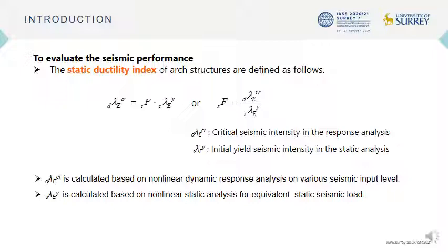Here, dλE critical is a critical seismic intensity in the response analysis. sλEY is a yield seismic intensity in the static analysis. If you can evaluate the value of sλEY and SF, you can easily estimate dλE critical as well.